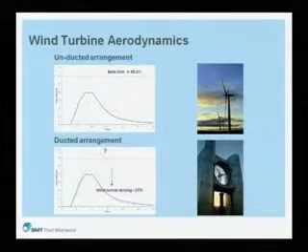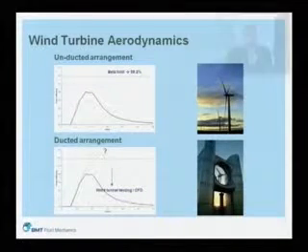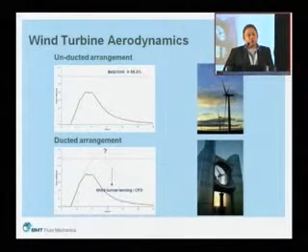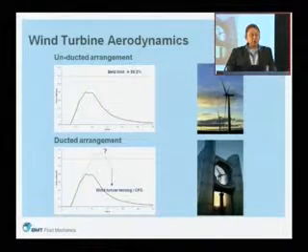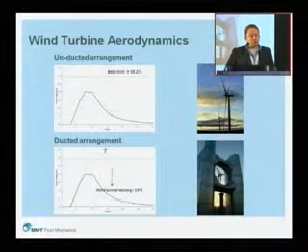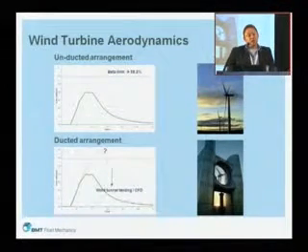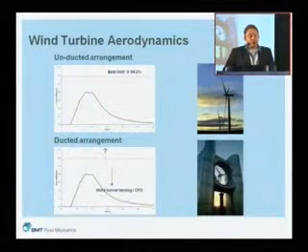I've mentioned the maximum theoretical efficiency that a turbine can see is 60%. That is true for wind turbines which are unducted and sit in open air. If you put a duct around it, and in some cases turbines operate in duct-like configurations on buildings, in theory you can get somewhat higher efficiency.